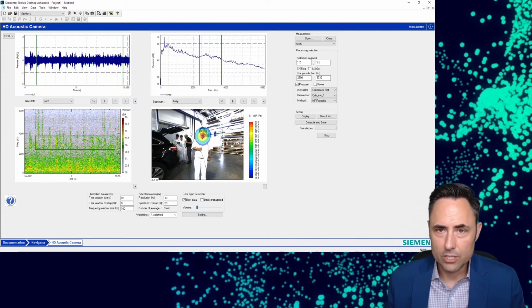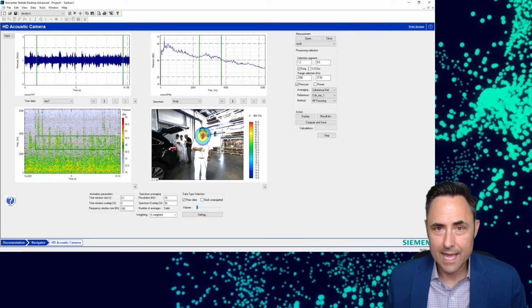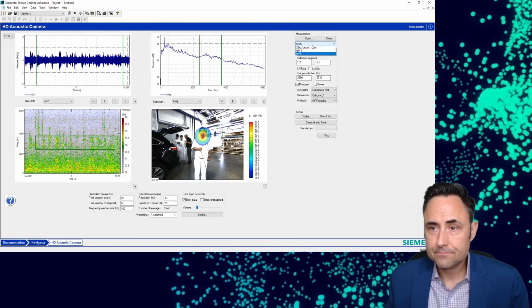It makes it really helpful to identify, say, is our wind noise inside our car coming from, you know, the wiper or from the wind seal leak that I have in the A-pillar. I can separate those two by adding an additional microphone and providing it some sort of coherent relationship. Okay, so that's one application.